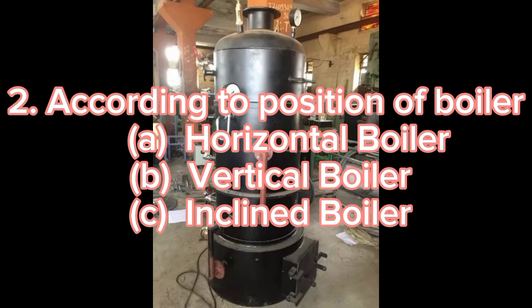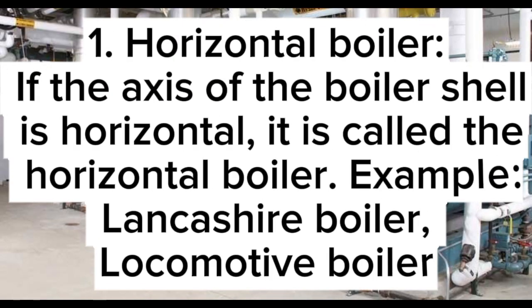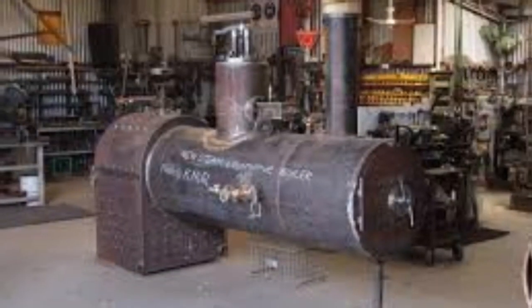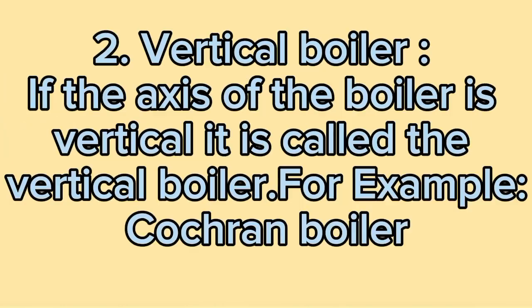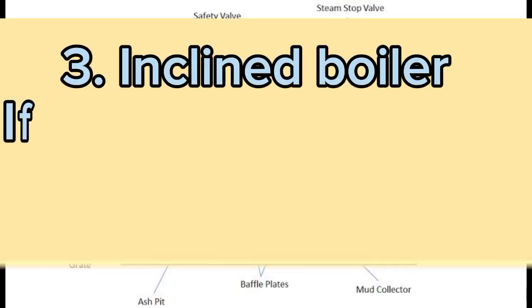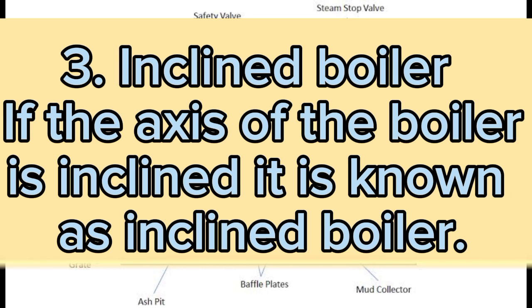2. According to position of boiler. 1. Horizontal boiler. If the axis of the boiler shell is horizontal, it is called the horizontal boiler. For example, Lancashire boiler and locomotive boiler. 2. Vertical boiler. If the axis of the boiler is vertical, it is called the vertical boiler. For example, Cochran boiler. 3. Inclined boiler. If the axis of the boiler is inclined, it is known as inclined boiler.